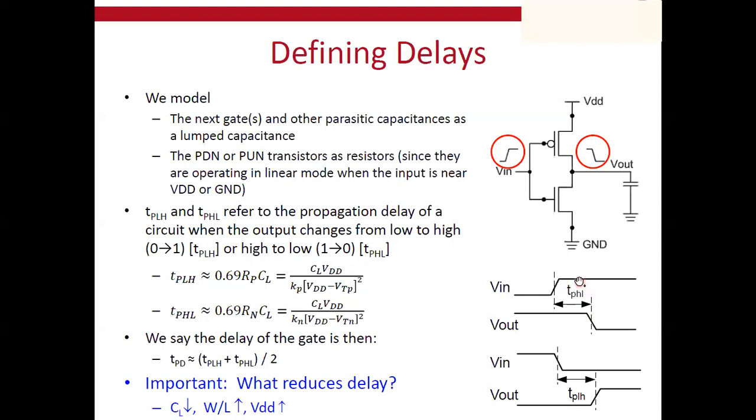After this propagation delay, the output will start to fall into a low, as you can see. Here is another, reverse example, when the input transitions from high to low. Again, it takes some time for the logic gate to register this change, and typically there is another propagation delay, as you can see. Here we call these tP high-low and tP low-high.